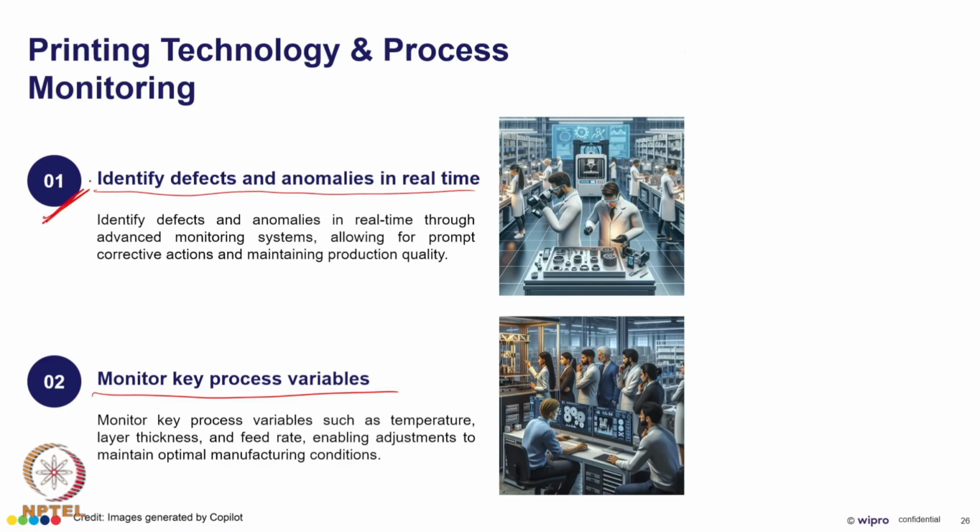And when it comes to identifying the defects itself, there are multiple sensors being used in LPBF technology to regularly identify whether any defects are happening in the build platform or not. In the case of LPBF technology, if distortion or blade damage is happening, then immediately a camera is able to detect any anomalies happening during the building time, and it is able to immediately stop. Not only in LPBF, even in the case of FFF technology, if a part is coming out of the build platform, then it is able to detect that the part has come out and it couldn't be printed normally.